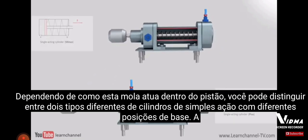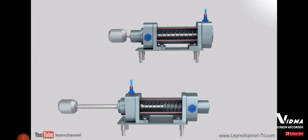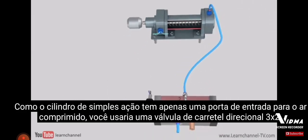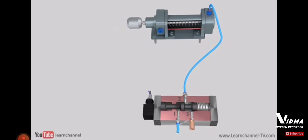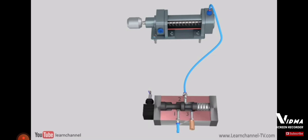Depending on how this spring acts within the piston, you can distinguish between 2 different types of single-acting cylinders with different base positions. Base position minus is the common one. As the single-acting cylinder has only one inlet port for the compressed air, you would use a 3x2 directional spool valve. In our example here, we use a spring-loaded directional valve.